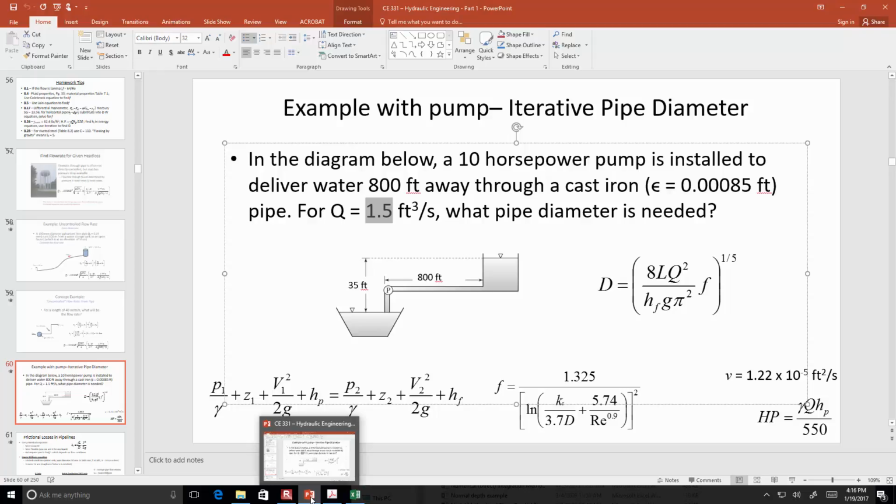My valve is a gate that closes down part of the way. When I crank it, it closes even more and even more, making this hole progressively smaller. Then as the water goes through here, it loses energy because it's squeezing through a smaller hole. So what a valve does is introduce a local loss, essentially.